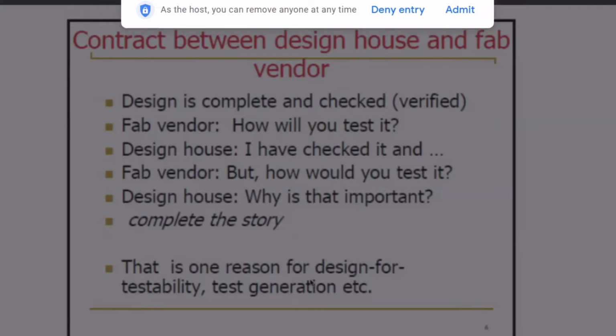Sir, what are the different methodologies that we use during testing in test generation? The same test methodologies are used for DFT also, after manufacturing. Basically, test generation is related to fault modeling. And DFT is related to that: you have an idea of the fault model, and you know what the fault site could be depending upon the fault model. Then you can apply different structures so that you can perform simulations by producing the input.